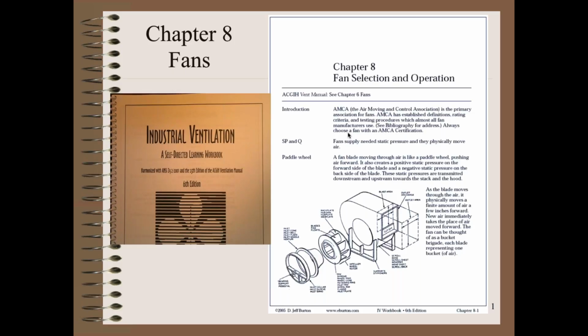Okay, so basically, we designed a suction system to pull contaminated air and contaminants away from the worker. We used a hood design that was appropriate. We then connected it to a ductwork system and to a filter, so that the air is moving fast enough to transport the material away from the worker through ductwork to somewhere where we can discharge it, get rid of it. Okay, so now before we get rid of it, sometimes we're going to put some sort of device to scrub the contaminant from the air.